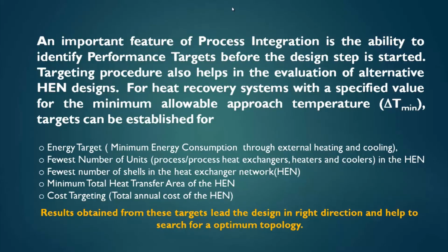Then the fourth is minimum total heat transfer area. The heat transfer area of a heat exchanger network gives a fairly accurate estimate of the cost of the heat exchanger network, and hence before the design it is always advisable to find out the minimum total heat transfer area as a target.